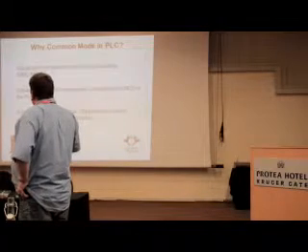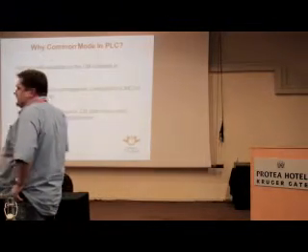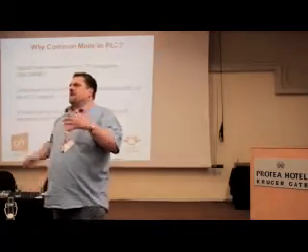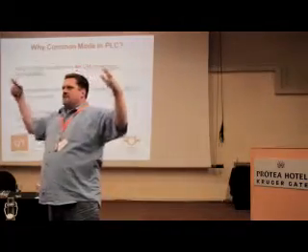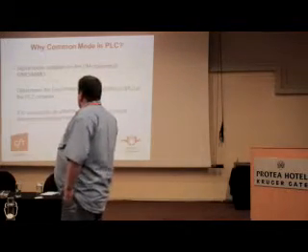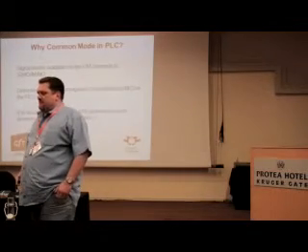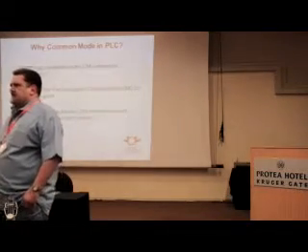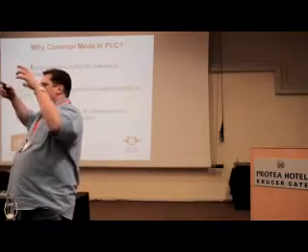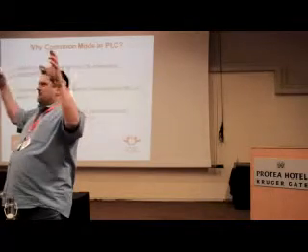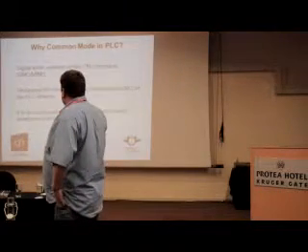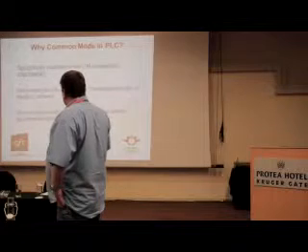Then, something that's close to my heart is the electromagnetic compatibility of the PLC network and its emissions. If we start emitting all over the power lines, that happens in common mode, with common mode current. I also did a paper last year at ISPLC, and I showed that you can actually communicate wirelessly or contactlessly with the power line network by using an antenna. That is also determined by the common mode, or the antenna current.